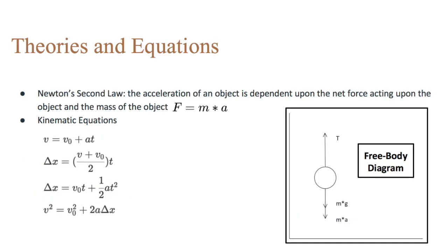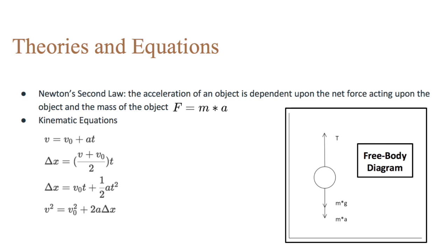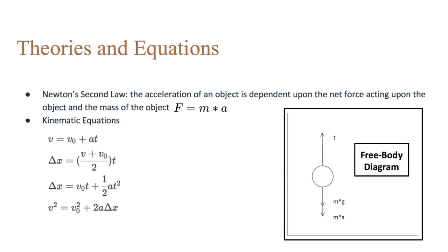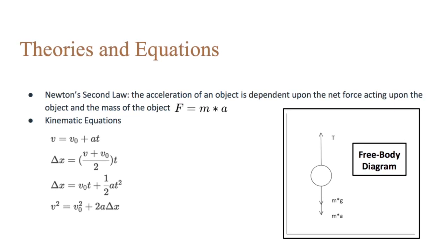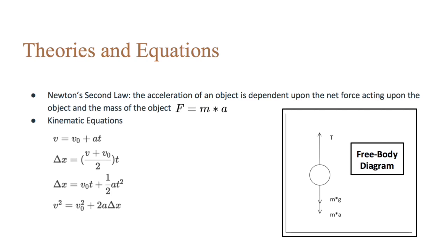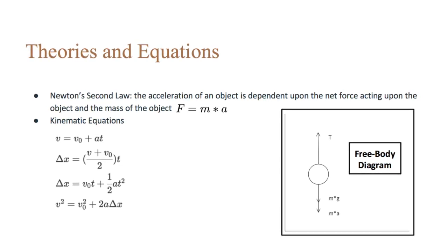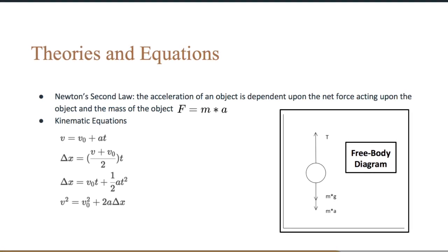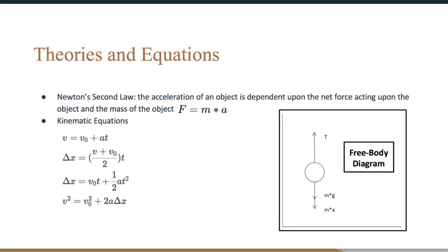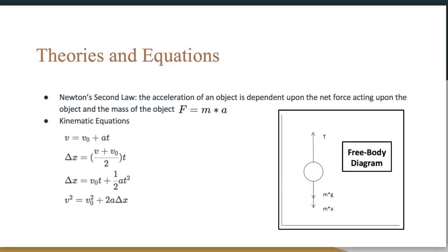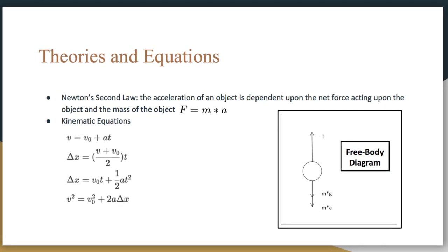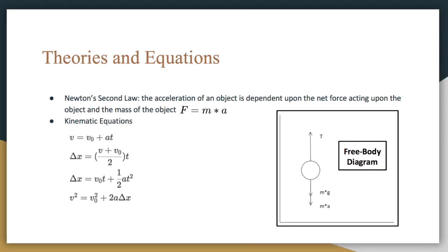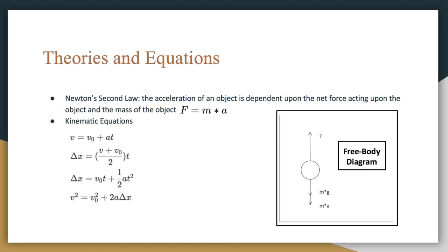In order to find the load capacity of the yellow bridge and the correct size for the Gorbel G-Force, we must take into account multiple different theories and equations of dynamics. The first equation of dynamics that we have to use is the kinematic equation v squared equals vi squared plus 2ad to find the acceleration of the G-Force that carries the product weight. Later, we have to use Newton's second law to find the dynamic load on the G-Force. And then we also have to use Newton's second law to find the load rating on the bridge. Lastly, we also have to analyze the entire system in static equilibrium to find the total design load for the bridge.